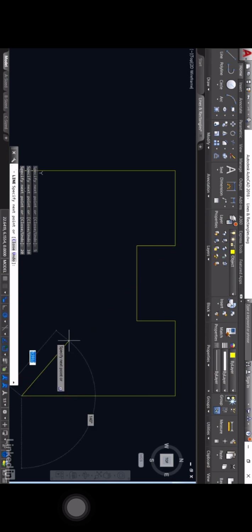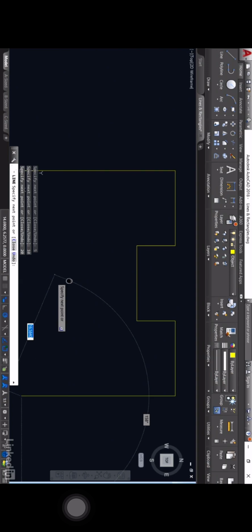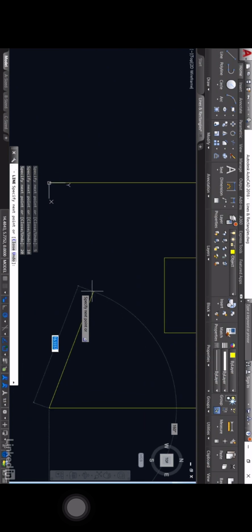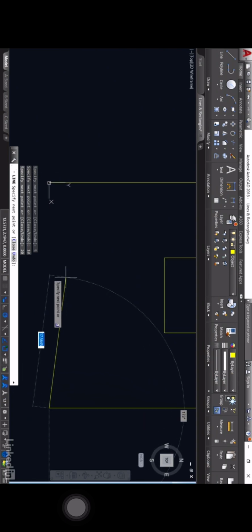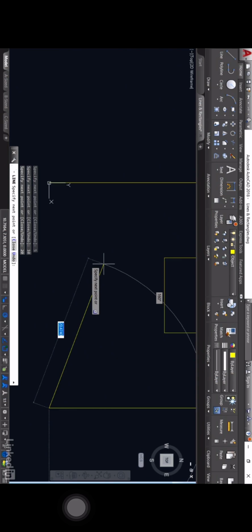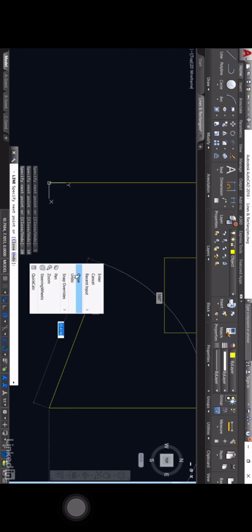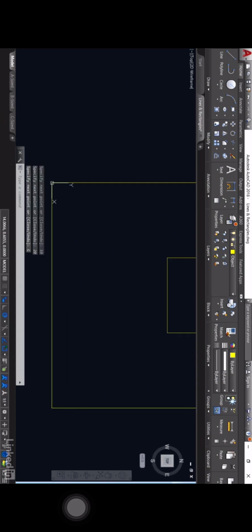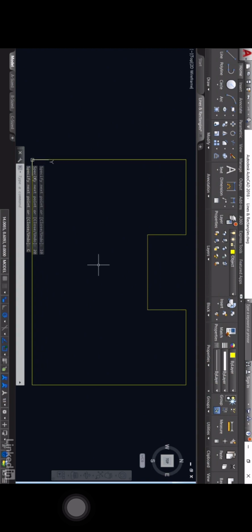Now, you'll notice I've got a shape there, but it's not fully closed. So if I pan upwards a little bit, you can see there that I need to take this line to that last point there. Now, what I could have done there is used object snap tracking if I wanted to, or there's a really nice feature if I'm drawing a continuous group of lines like I have done, where I can just right click on the mouse, and if I go to close, that closes the shape, and as you can see I've got the shape in place like so.